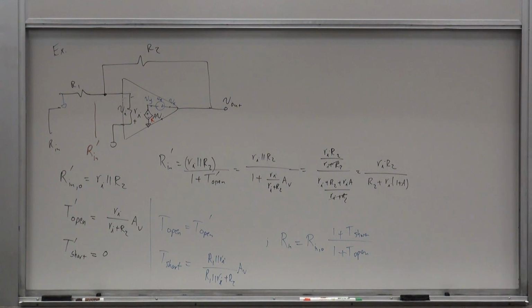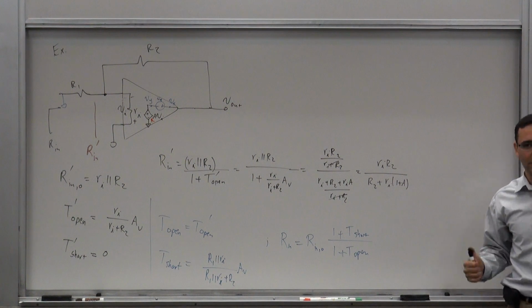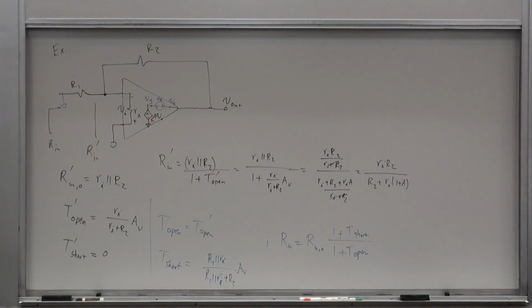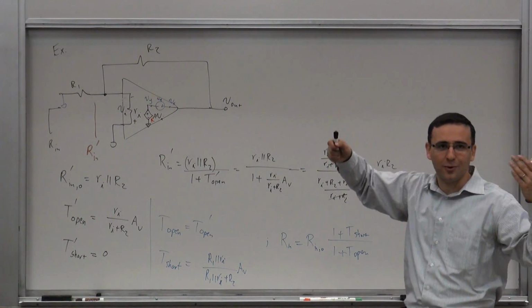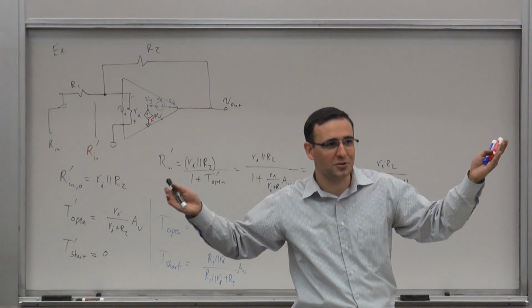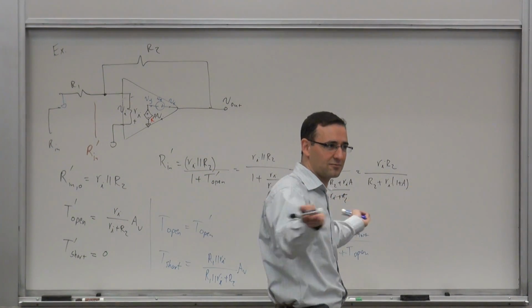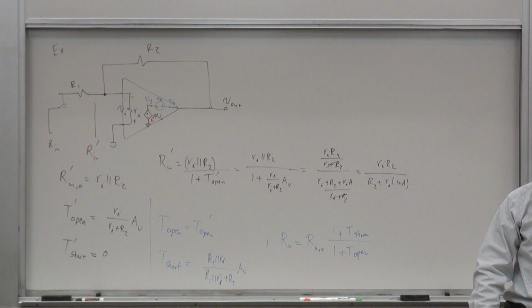So current mode logic is basically one where you have a high impedance drive driving low impedance nodes. And a voltage mode drive is when you have a low impedance source driving a high impedance load. Now, then the question is, is it still current mode drive? If I increase the impedances, what is low, what is high, where do we go from current to voltage? It's numbers.